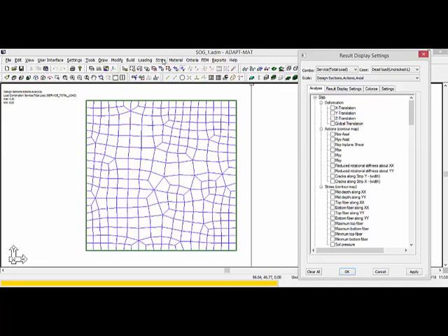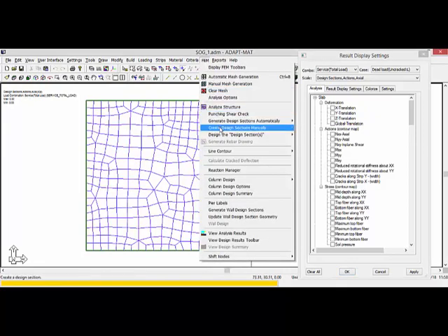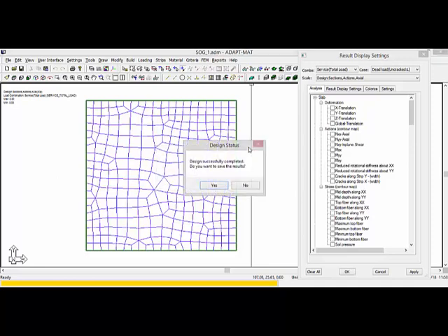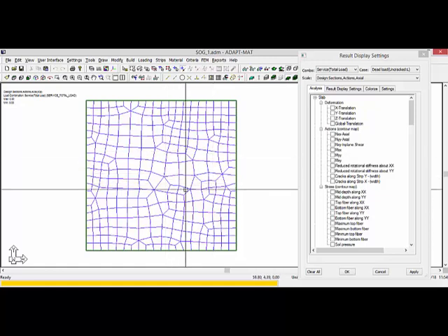If I take this a step further and I design the design cuts, this is where the program considers this effect of the nonlinearity, where we have additional capacity of the slab because we're going beyond the initial crack state of this slab, and we're relying on the fiber's properties to provide that response for us. So we'll go ahead and we'll say OK. We want to save that.